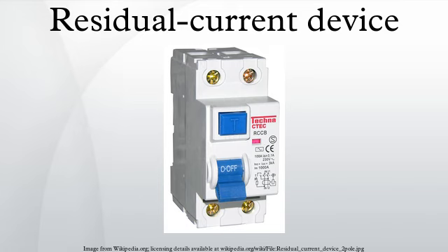More than one RCD feeding another is unnecessary, provided they have been wired properly. One exception is the case of a TT earthing system where the earth loop impedance may be high, meaning that a ground fault might not cause sufficient current to trip an ordinary circuit breaker or fuse. In this case a special 100 mA trip current time-delayed RCD is installed covering the whole installation, and then more sensitive RCDs should be installed downstream of it for sockets and other circuits which are considered high risk.